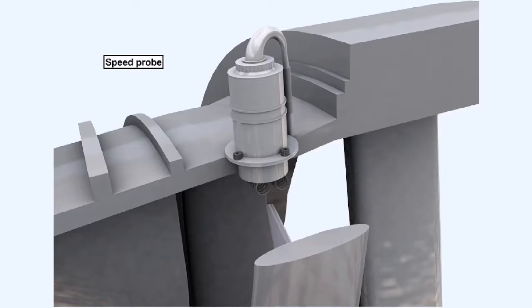It's probable that there would always be provision on the high-pressure compressor spool for driving a tachogenerator through the external gearbox, which is driven by the high-pressure compressor shaft. But it may not always be possible to have gearboxes driven by the other compressor shafts. In this case, a speed probe could be used. There are two ways that the speed probe can generate the pulses required to feed the system. The first method uses the fan blades to excite the magnetic field of the sensor head of the speed probe as they pass it. The excitations generate a waveform which has a frequency proportional to the rotational speed of the fan.